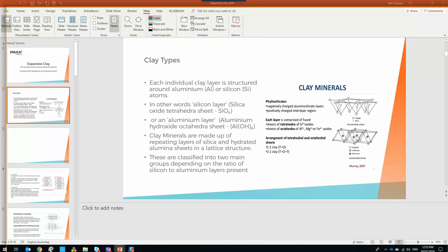What about trees around footings? Trees just suck moisture content out, and they're more a problem in M-type soils where the failure mechanism is generally due to dry conditions, but with blacks and expansive soils, it's dry, wet and everything in between.